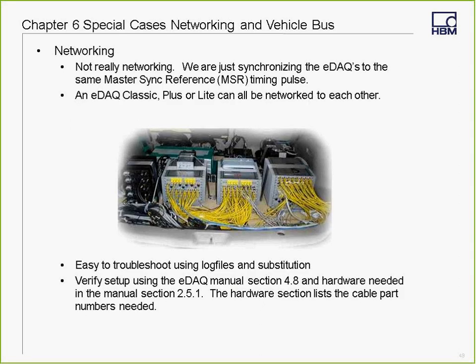Chapter 6. Okay, special cases, networking, and vehicle bus. Okay, look upon networking as nothing more than synchronizing multiple eDAQs off of one master sync reference timing pulse. Okay, quite honestly, any infinite number of eDAQ classics, pluses, or lights can all be networked to each other. So if you have a classic, a plus, and a light, and networking cables, you can get all three of them to work together.